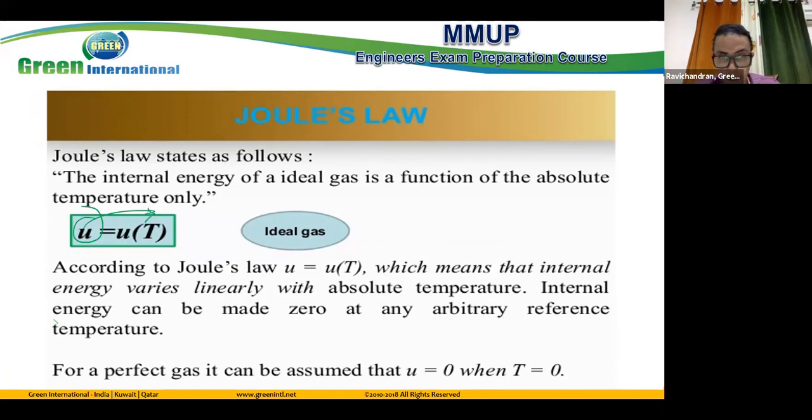And also, according to that, enthalpy is equal to U plus PV. We solved this equation last session. Specific enthalpy equals specific internal energy plus pressure times specific volume. So U is a function of temperature only, and if you check PV, substituting the ideal gas equation, PV equals nRT.